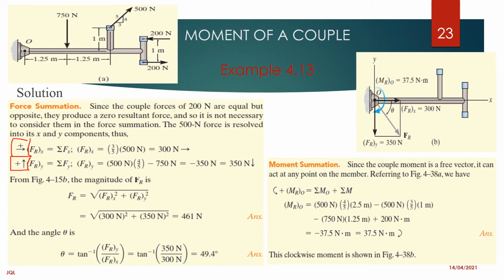For the angles, as I was just explaining, for a component in the x-axis, because the x-axis is supposed to be horizontal, that is our x, and the vertical, that is our y. For the force in the x, it's just multiplying by the component which is horizontal, which is 3 over the 5 times that force, which is the 500.